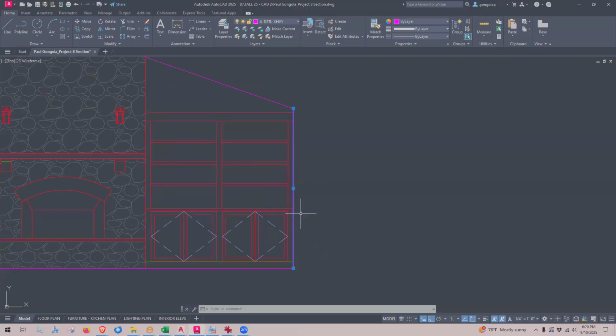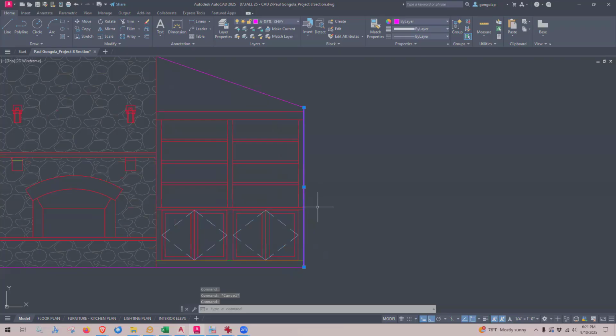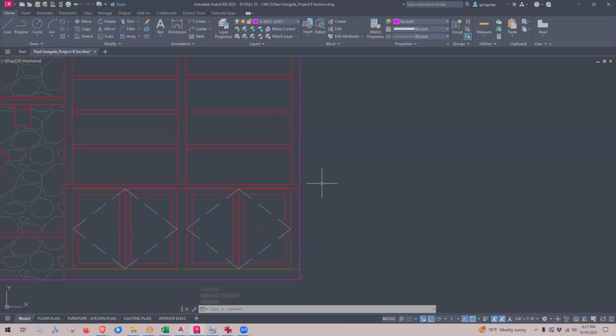And it's a drywall wall, so this line is going to have some thickness. Drywall is usually either half inch if you're doing cheap construction, or 5/8 of an inch if you're doing higher quality construction. And we're going to do quality construction.